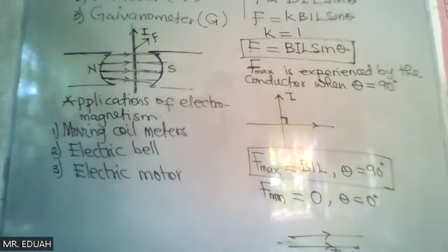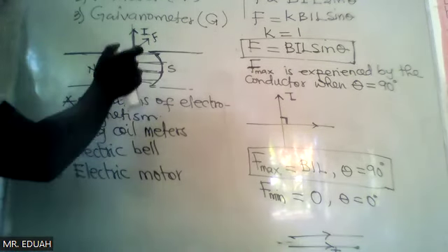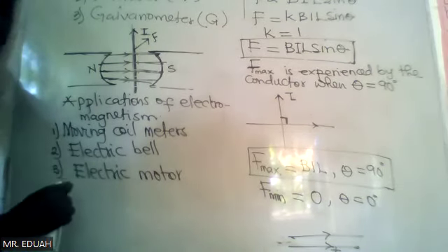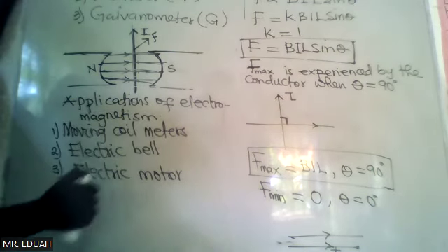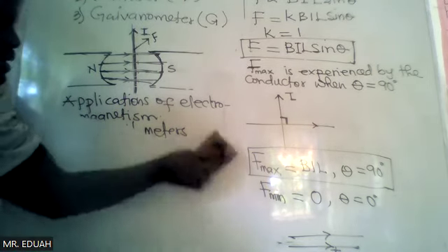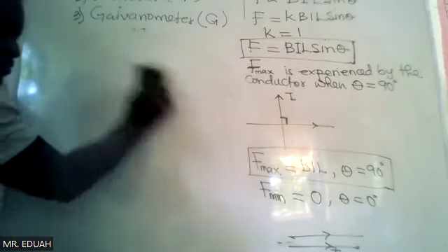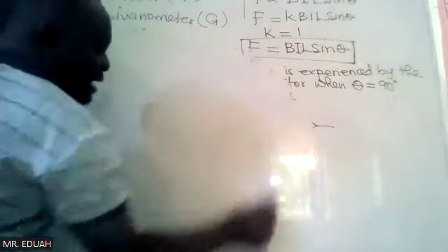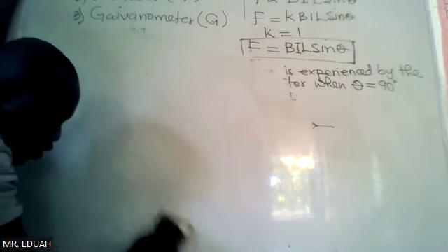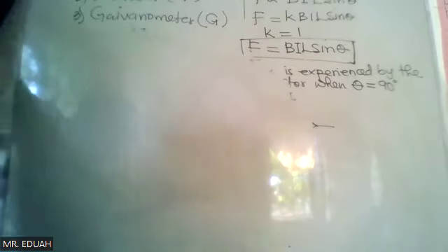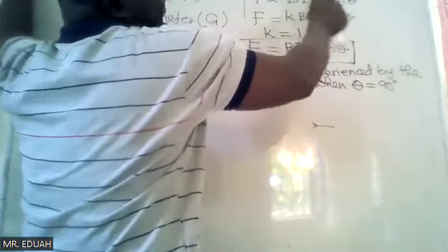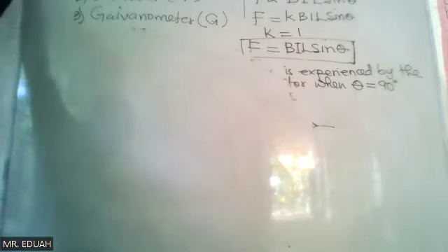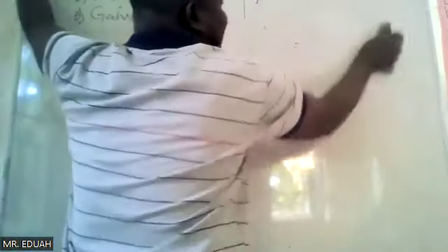All right, so let's look at the moving coil meters. Now, the ammeter is used for measuring current flow in a circuit. And so an ideal ammeter must have very low resistance, almost zero resistance, so that it wouldn't have any opposition and it can always measure a maximum current, or optimum current.